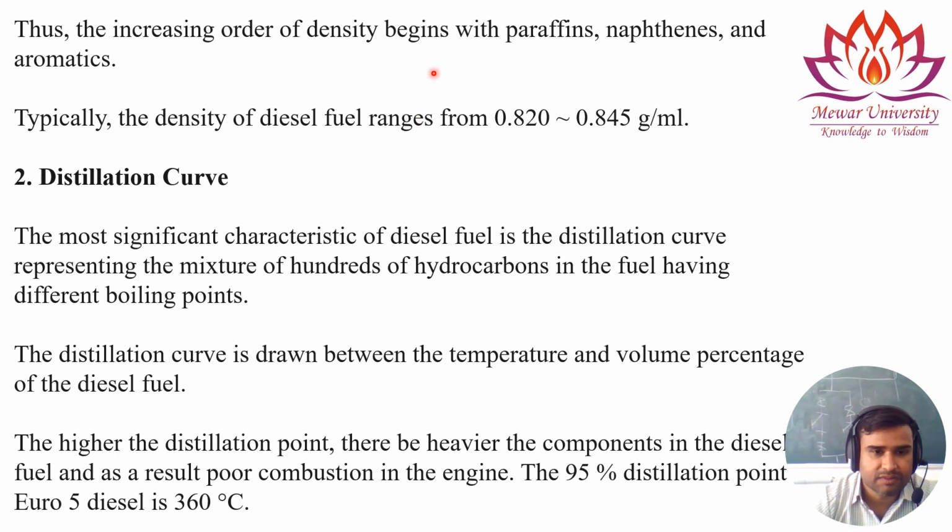If the density increases, that means the diesel has more carbon molecules, or the percentage of paraffin, naphthalenes and aromatics increases. Now, another characterizing property is the distillation curve. The most significant characteristic of diesel fuel is the distillation curve, which represents the mixture of hundreds of hydrocarbons in the fuel, having different boiling points.